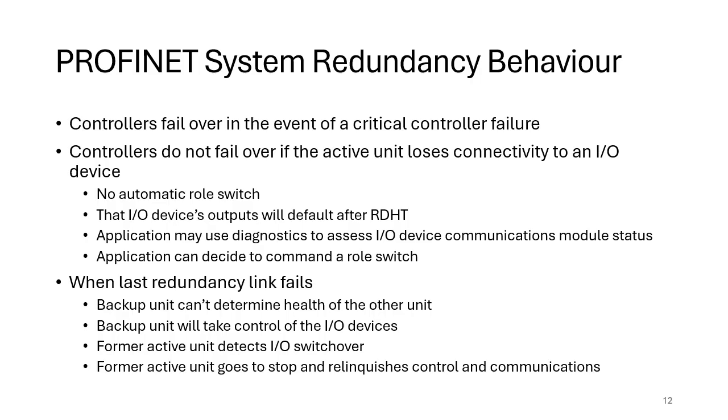or it might be if the controller experiences some catastrophic fault. For example, maybe there's a memory fault, maybe there's some sort of subsystem fault that causes the controller to stop. But the idea is, under normal circumstances, you've got a master controller with a backup, and it fails over from the master to the backup in the event of this critical failure.